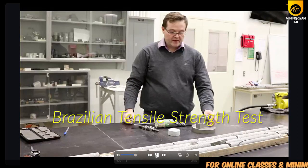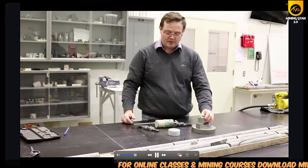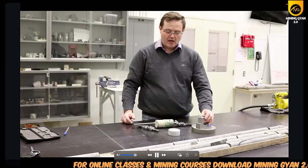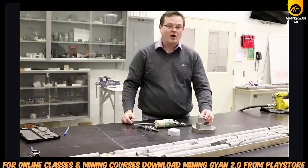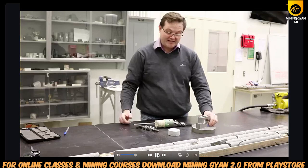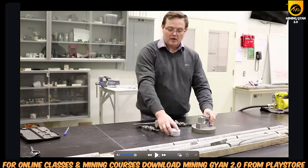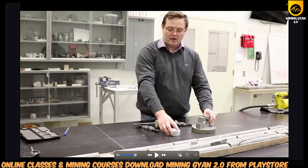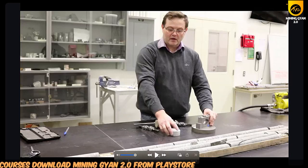In today's experiment, we're going to look at the Brazilian test, which also helps us to find out the tensile strength. Because I told you when I was discussing the tensile strength that we cannot find out the tensile strength directly, so we find it out indirectly with the help of the Brazilian test.